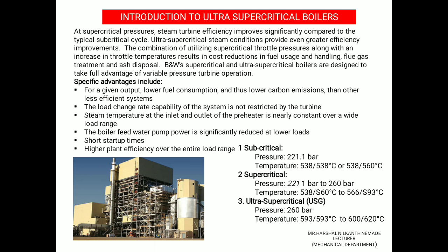So what are the advantages? Specific advantages include, for a given output, lower fuel consumption and thus lower carbon emission than other less efficient systems. The load change rate capability of the system is not restricted by the turbine. Steam temperature at the inlet and outlet of the reheater is nearly constant over a wide load range. The boiler feed water pump power is significantly reduced at lower load. Shorter startup time and higher plant efficiency over the range.